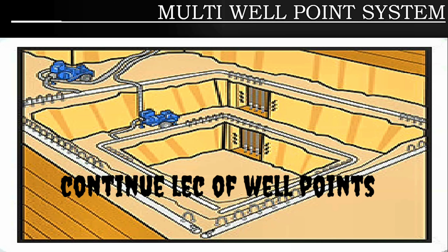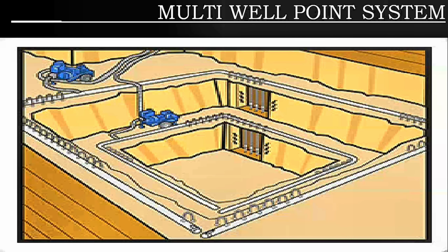If any students ask me, for example, "Sir, I need to go more than 10 meters," or I have the solution, I need to provide the solution to my exterior engineer, that if you have to lower the water down up to 12 meters or 13 meters, then what you need to do. So for that condition, we have the multi-well point system.